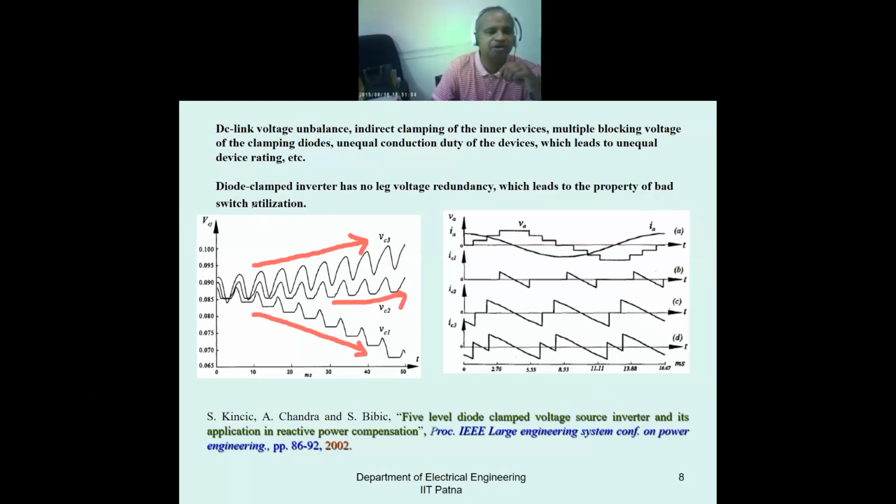That means all the capacitors have different equivalent series resistance, and that is why they charge differently. How to equalize this is one of the biggest problems today in the diode clamp converter. But nowadays, when your design is perfect, it will charge nearly equally. So I will tell in the last section what the design aspect of this is.